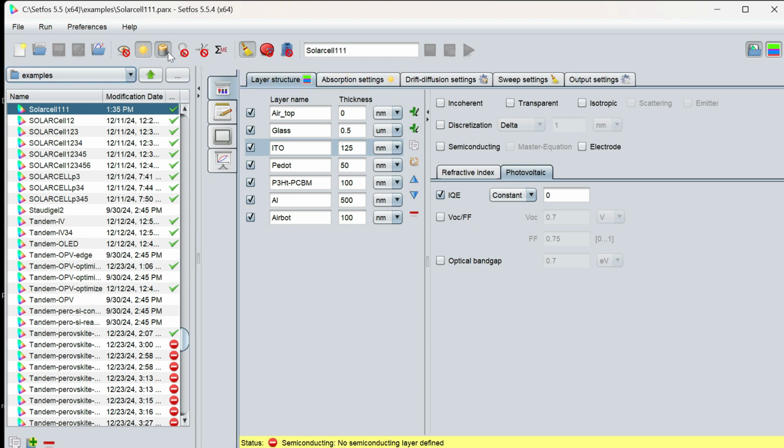So for the electronic solar cell simulation, we need to activate the drift diffusion module. In this section, we will learn the optical and electrical behavior of bulk heterojunction organic solar cells. This tutorial is generally based on the previous optical simulation of the solar cells. So here, to couple the generated charge with the drift diffusion equation, we need to activate the drift diffusion module. Here P3HT:PCBM is working as the active layer.